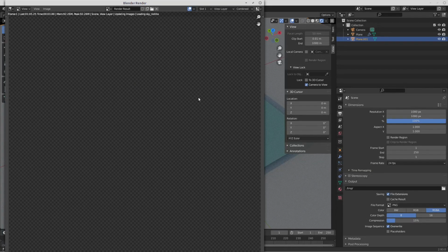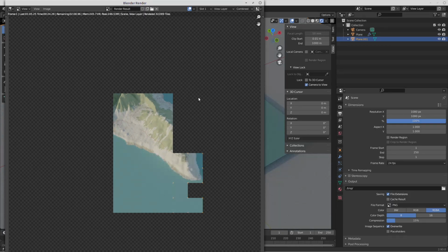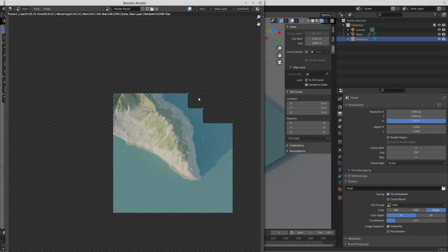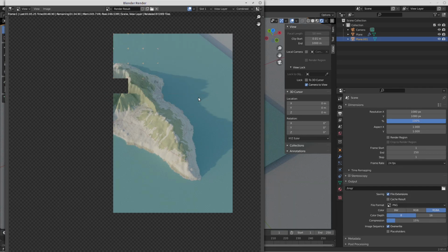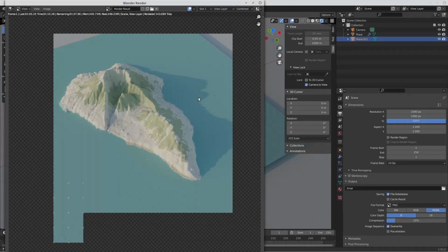So hopefully this has given you enough information so you can do this yourself by generating elevation images and a map image. And it doesn't have to be OpenStreetMap. It can be anything. It can be a satellite layer or whatever you want. And you can play around with the light, the amount, the strength of the displacement. And you can animate the 3D scene into a movie. You can add 3D objects that you create yourself or that you import from some form of source from the internet. And yeah, Blender is extremely powerful, and you can do really a lot with it.